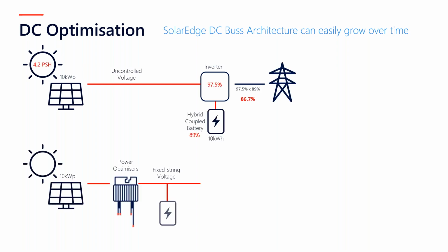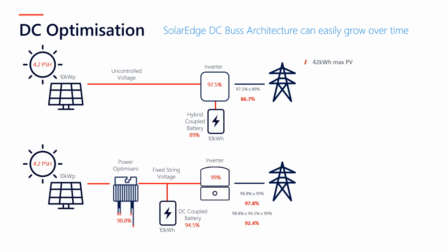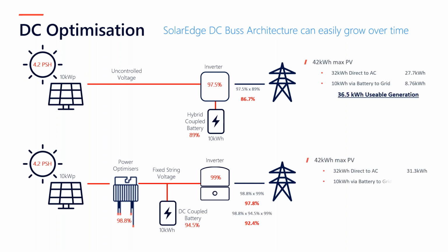And I'm just going to move through this quickly, but this also is a worked example comparing the differences between traditional DC coupled hybrid technology and that which we see with our own systems. So again, we run at fixed voltages, and because the battery charges at the same voltage as that which is generated on the roof, it's extremely efficient. It's quite different to traditional DC coupled hybrid inverters, where there's some sort of voltage management or step down or step up effect, which can be nearly as inefficient as a DC to AC inversion step like we see with AC coupling.